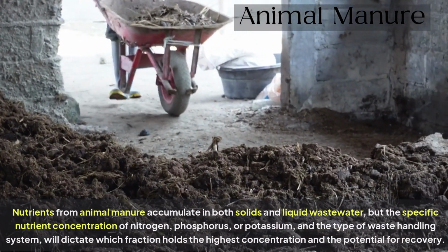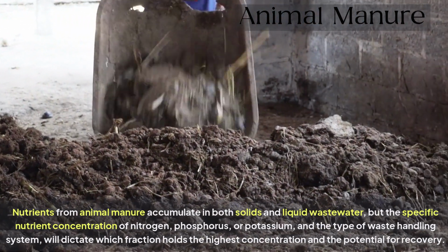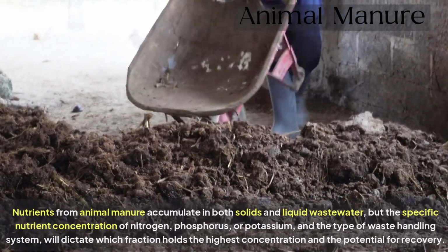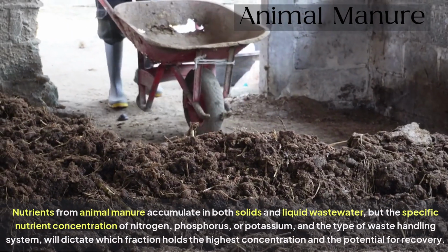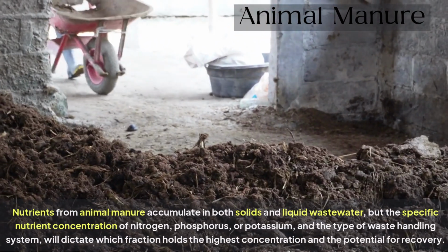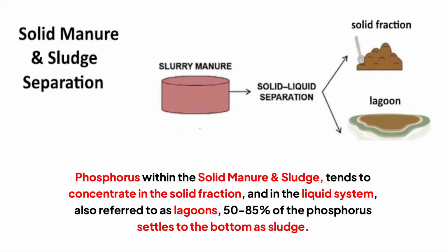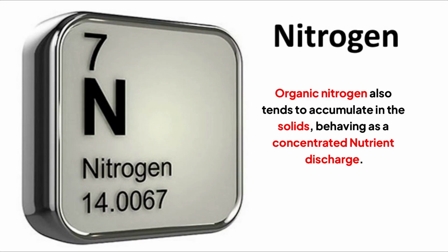Nutrients from animal manure accumulate in both solids and liquid wastewater, but the specific nutrient concentration of nitrogen, phosphorus, or potassium, and the type of waste handling system, will dictate which fraction holds the highest concentration and the potential for recovery. Phosphorus within the solid manure and sludge tends to concentrate in the solid fraction, and in the liquid system, also referred to as lagoons, 50 to 85% of the phosphorus settles to the bottom as sludge. Organic nitrogen also tends to accumulate in the solids, behaving as a concentrated nutrient discharge.